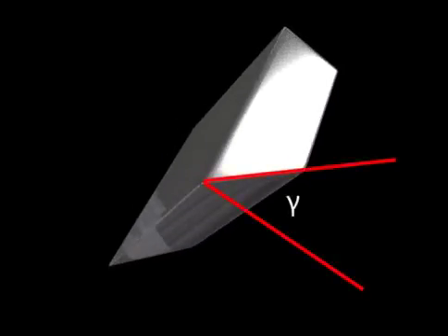The relief angle is required to prevent excessive rubbing on the heel of the knife when cutting. Without enough clearance, high amounts of friction can heat up and weaken the blade. Also, the rubbing can smooth the surface of wood, making later finishing stages difficult.